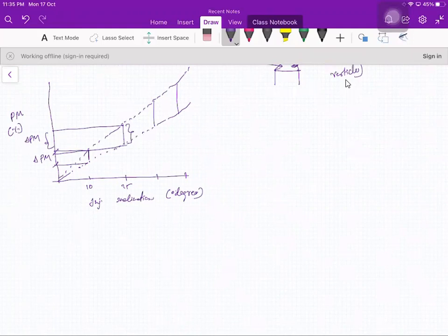In four-valve engines, symmetric air motion in the piston bowl and equal fuel distribution between different sprays lead to optimal mixture formation and combustion with very low smoke levels.